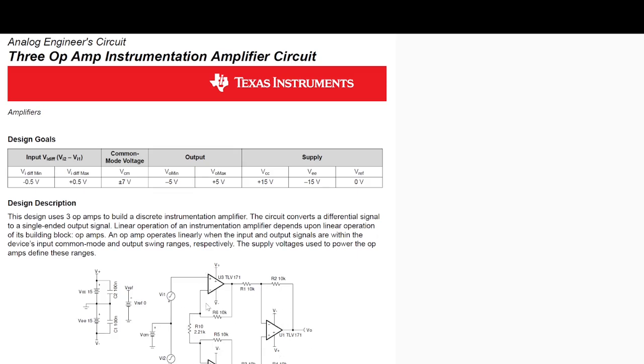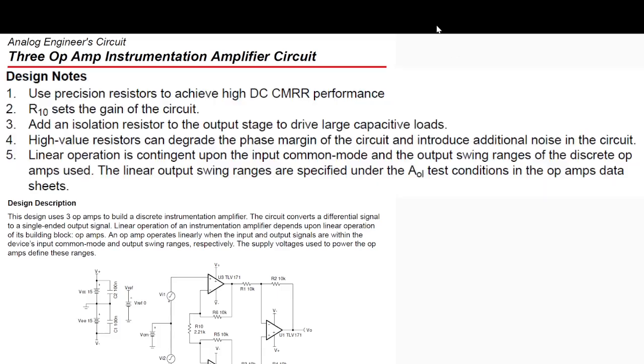So as you can see here, it's using 3 OPAMPs within one IC in order to achieve, as I said, significant gain. But your gain, I think I already told you, cannot go beyond the supplied voltage. Okay, so the gain will be limited to the applied voltage. Very important, both plus and negative side. Depending on your application needs, you make sure that you use the proper supply voltage to achieve the desired objectives.